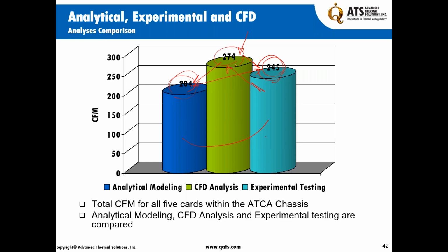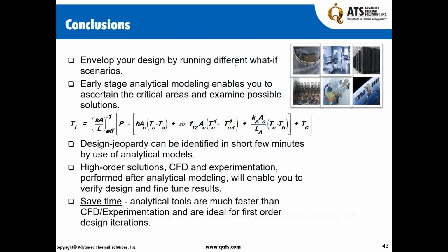Now I can walk into my design team and say, I have a high degree of confidence based on the information and the boundary conditions you've given me, the power, the temperature, etc. I have a solution that's going to work. Our junction temperature is going to be X. We need a heat sink of certain performance. Our fans have to be Y with certain voltage and volumetric flow rate in order to meet our requirements. So the basics of the design is done. Now the rest of it is for the mechanical packaging team or the circuit engineers to go and put this information together and make sure they deliver for you what has to happen.